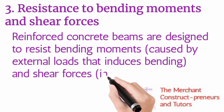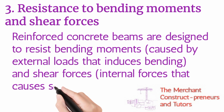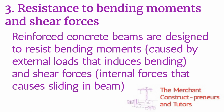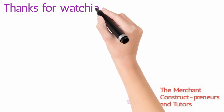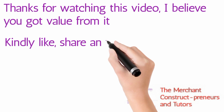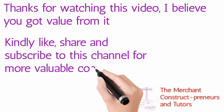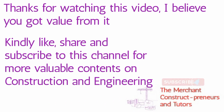Then the third one is the resistance to bending moments and shear force. Now, reinforced concrete beams are designed to resist bending caused by external loads that induce bending. What this means is, as the loads are on top, whether for walls or anything that the beam is bearing, at the center, when you have a slender beam, once you apply load at the center, it is going to tend to bend.